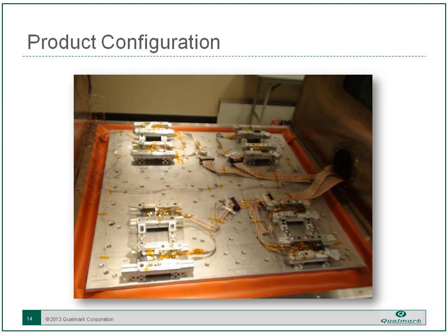The configuration of a product in HALT is often stripped down to subassembly level to ensure maximum stresses for the most effective HALT. However, this changes for HASS, where products are often screened as an upper-level assembly. Similar to product orientation, the change in configuration will affect the response. Understanding the change in configuration will help you understand and deal with the change in product response for HASS.